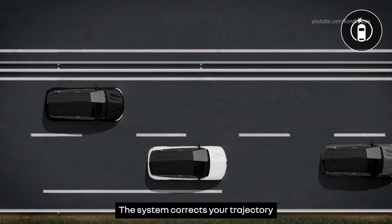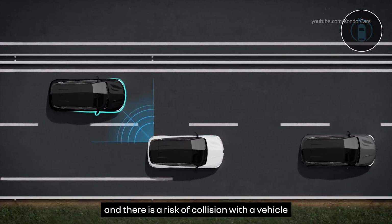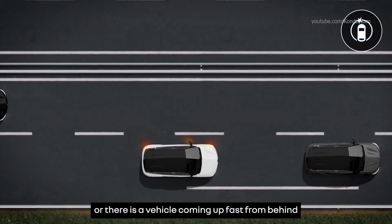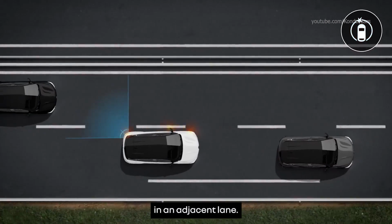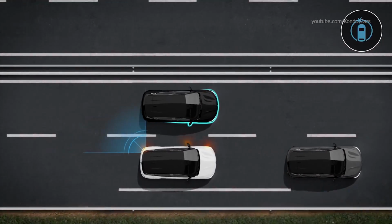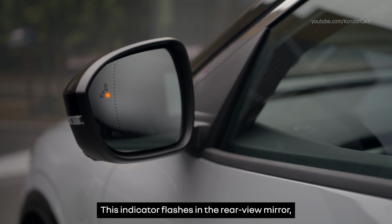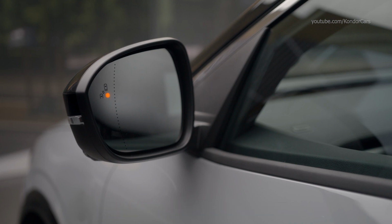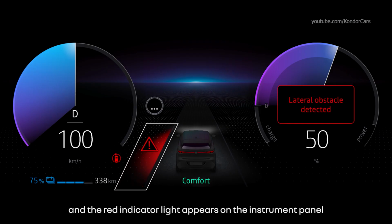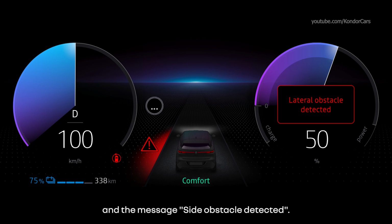The system corrects your trajectory if you're approaching a line and there's a risk of collision with a vehicle behind you in your blind spot, or there is a vehicle coming up fast from behind in an adjacent lane. This indicator flashes in the rearview mirror, and the red indicator light appears on the instrument panel with an audible signal and the message "Side Obstacle Detected."